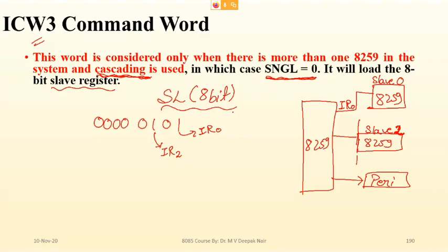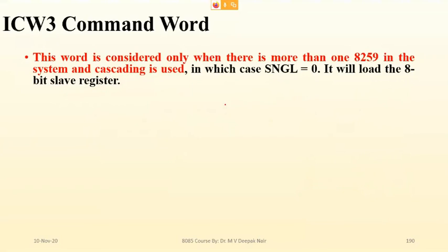Then one more thing, there are so many things that you have to remember. That's the challenge here. Anyway, 8085 can only write on these particular slave bits. The slave register, it cannot read back. 8085 cannot read back the slave registers. Anyway, you cannot remember all these things. There are so many other things also.